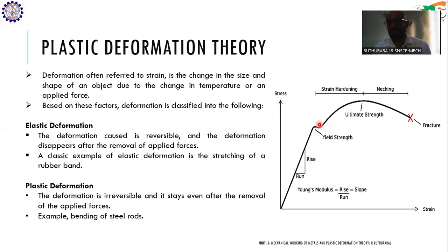What happens is that once elastic deformation occurs, sudden breaking will happen. When you stretch a brittle material, for example, a glass, minute elastic deformation may be there. But what happens when you stretch the glass? It will break suddenly. So sudden breaking is the characteristic of a brittle material. When a material breaks suddenly, you cannot use it in a load-bearing application.